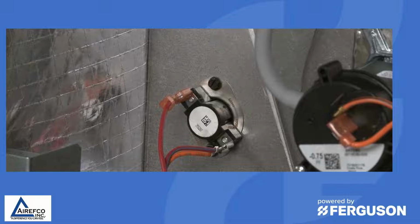Your more modern furnaces have a click-on type high limit switch that inserts into the heat exchanger compartment. And these switches will trip, and as we said, they are auto resets. So if the temperature drops below the set point, the furnace will reset and will reignite. Causes for the limit switch to trip are, in some rare cases, the switch might trip at a lower temperature than what it's designed for. But often it's because of gas pressure, gas firing rate, or turbulence in the furnace causing this limit switch to trip.